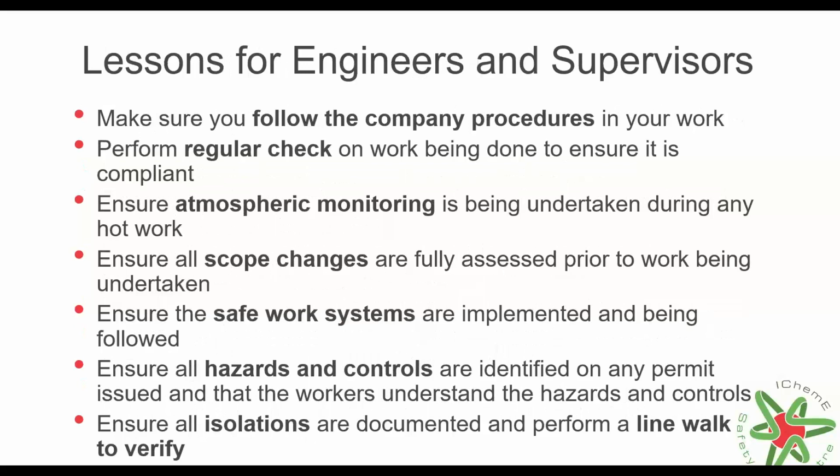For the engineers and supervisors on the site, you need to make sure that you follow the company procedure in the work that you're actually doing. You should be performing regular checks on the work that's being done as a supervisor to ensure that it's in a compliant manner. Ensure that atmospheric monitoring is being undertaken during any hot work. Ensure all scope changes are fully assessed prior to the work being undertaken.